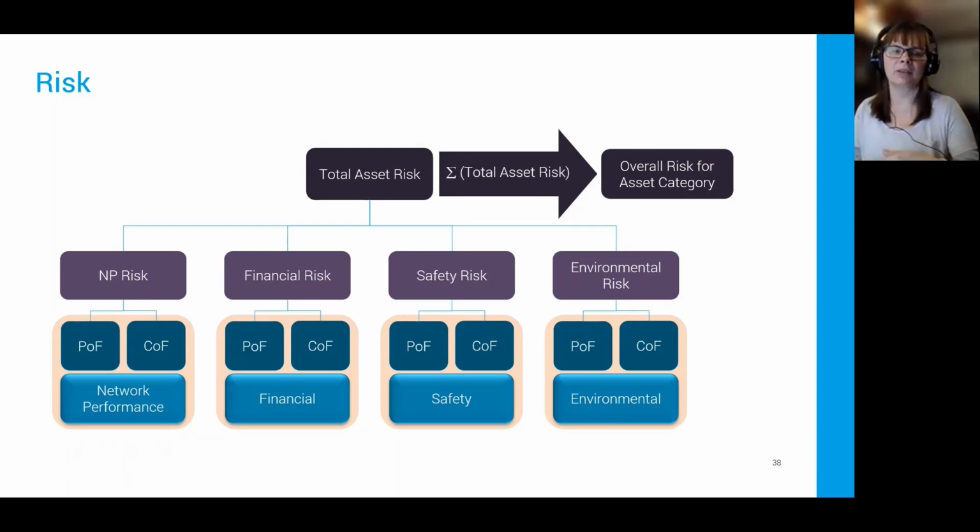And so you can work out the residual risk of replacing individual assets, and therefore you can work out what we call the delta risk, so the difference between the current risk or the future risk and that residual risk, and that will give you the amount of risk you will reduce off the network by replacing each and every asset. And so you can work out which are your highest contributors to risk, and you can use that as a prioritization for replacements going forward.